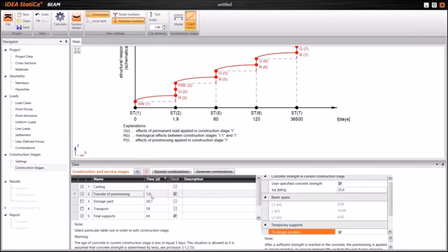This 1.9 is still quite a long time. It should be less than 1 day, definitely, I know it, but it is equivalent age, in which the concrete would mature to the same level, 25 megapascals, when we have 20 degrees Celsius.